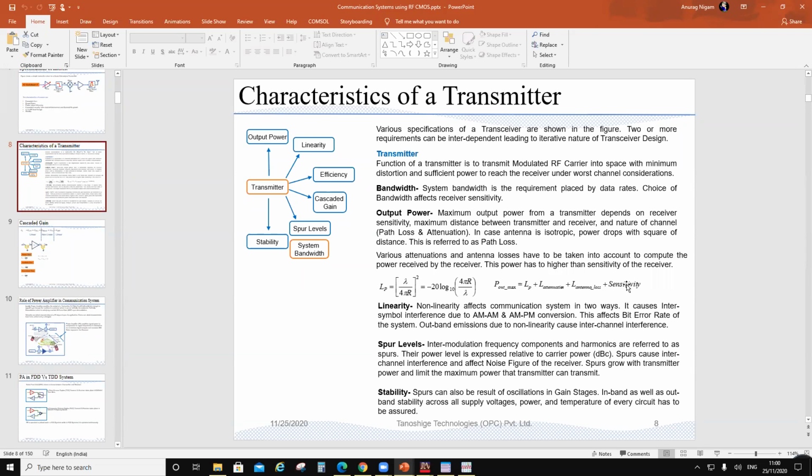Now you have the sensitivity of the receiver. Now add that, if that comes around something like 19 dBm, that's what commercially people are doing, then your compression point is around 25.7. And then you design for 25.7 compression points. So the TOI is going to be 11 or 12 dB above that. And then SOI would be above that. PA gain is taking 20 and TOI 14. PA gain is 20 and TOI is 14.